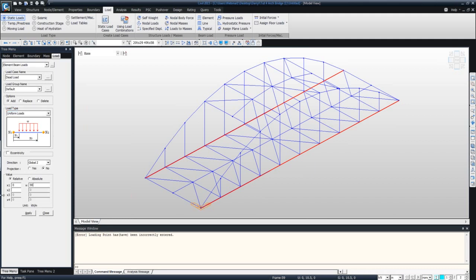There we go. And then you just apply it using this function here. So x1 and x2 determine the position of your loading, the start and the end position, and then weight is the weight of the load itself. So that would be how you would apply these loads here.